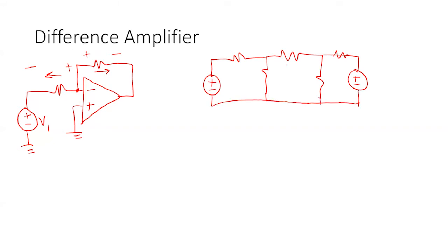The reason I never like this is because if I do the KCL at this node, this picture bothers the crap out of me because I know the current goes one direction in this middle resistor, not two ways, right? It can't. What's going to happen is this guy is going to be 1 amp and this guy is going to be minus 1 amp. So they actually are the same thing. I just don't like that. I never have.